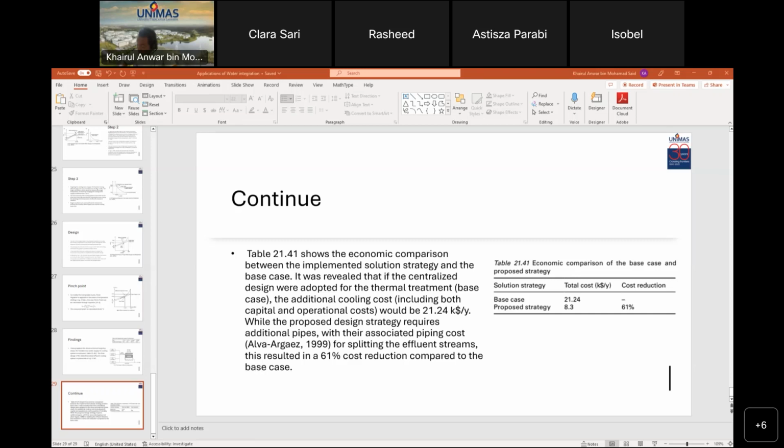So the temperature limit for return cooling water is required when cooling water treatment is important. Also, if plastic packing is used in the cooling tower, it should be able to take the required increase in temperature without deforming or degradation. This will cause a deterioration of cooling tower performance.